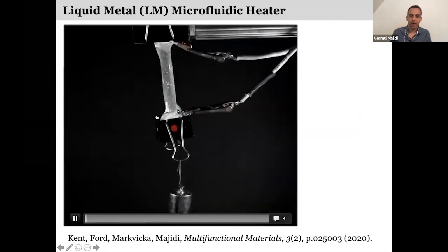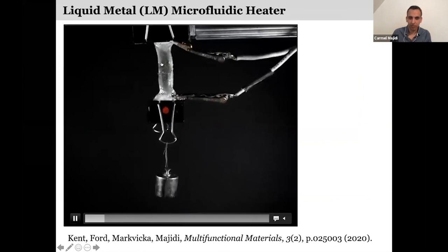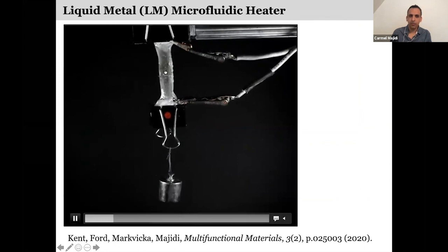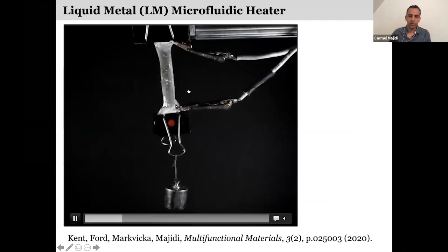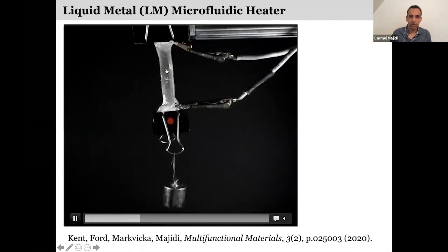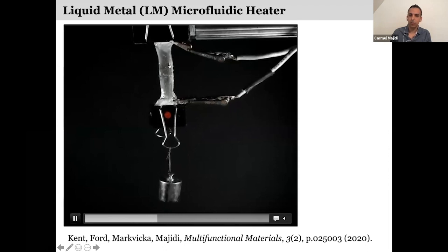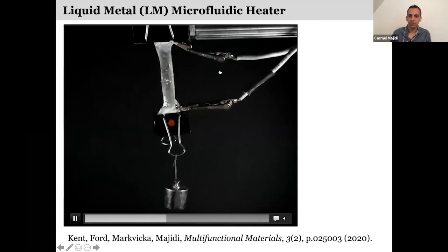And here's that actuator. It's tough to see the liquid metal traces just because they are fairly thin. We get fairly good resolution with the UV laser micromachining, but still, there's enough electrical connectivity there to pass electrical current through and induce that phase change.